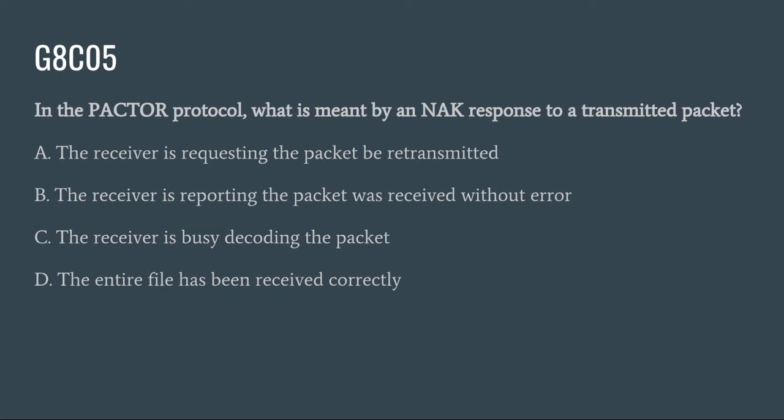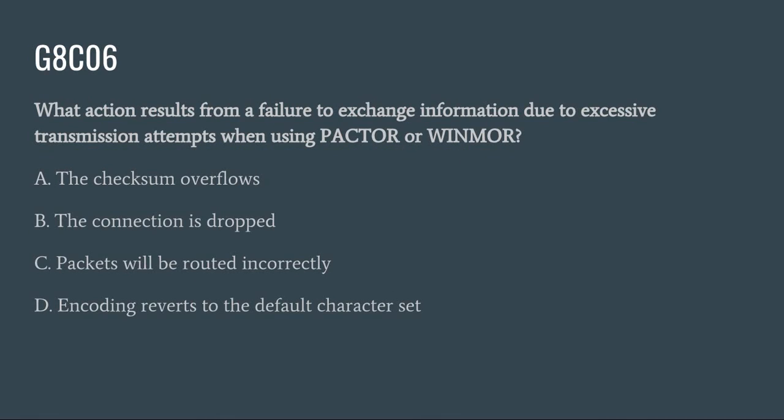G8C05. In the Pactor protocol, what is meant by the NAK response to a transmitted packet? A. The receiver is requesting the packet be retransmitted. B. The receiver is reporting that the packet was received without error. C. The receiver is busy decoding the packet. Or D. The entire file has been received correctly. Correct answer here is A. The receiver is requesting that the packet be retransmitted.